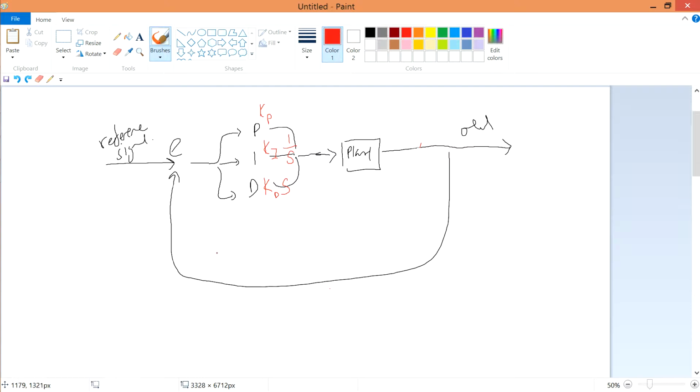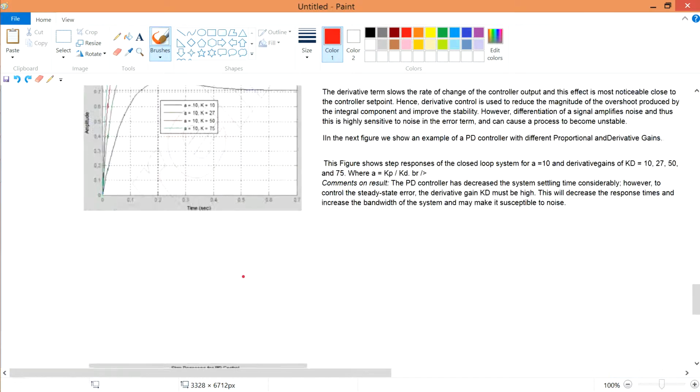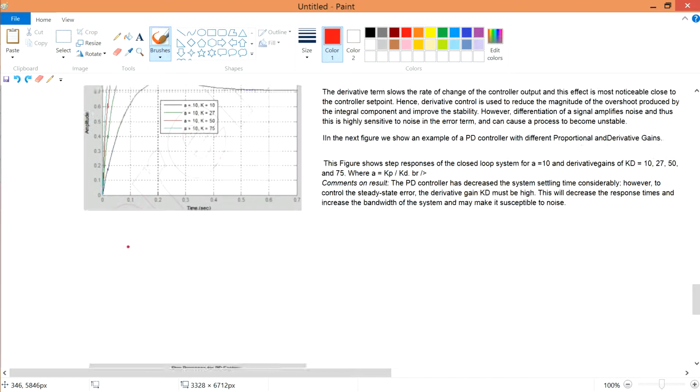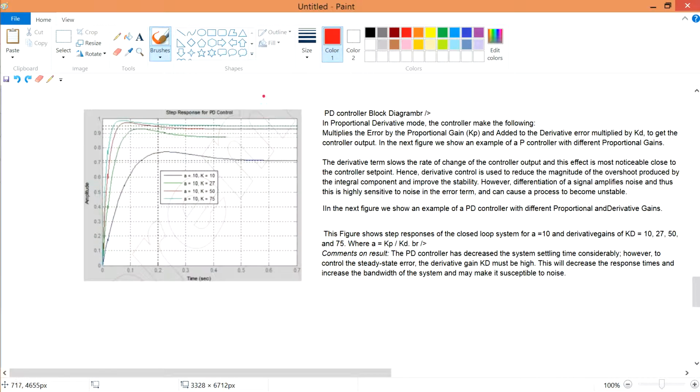And if the overall system is mixed with your controller, and your error itself is together with the noises already, the disturbances, and therefore if your error controls this overshoot, in the PD controller, and you control the overshoot such that it's pretty smooth, you can also amplify the noise, because you're allowing the noise to mix together with your reference signal.